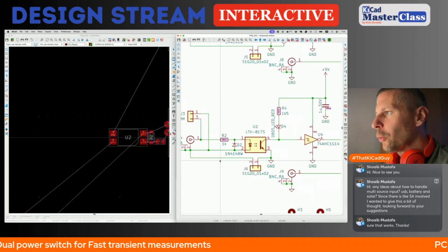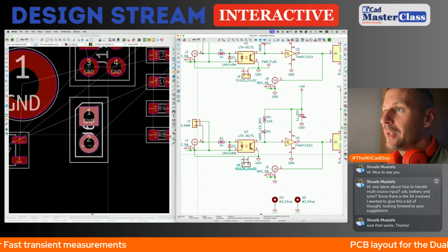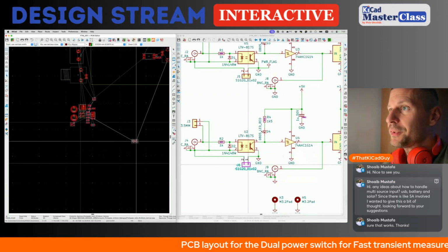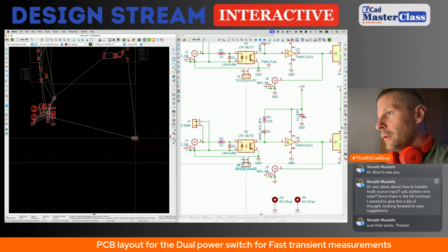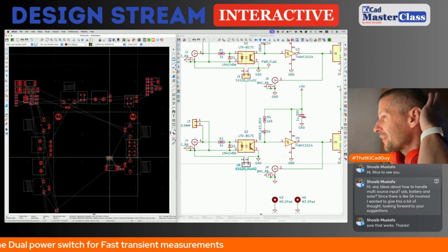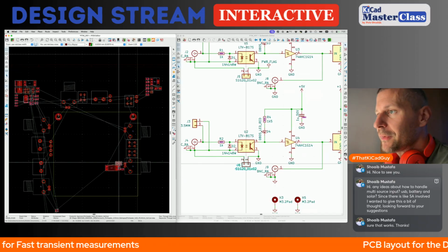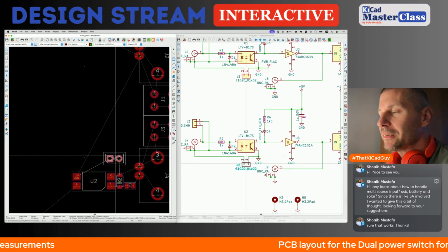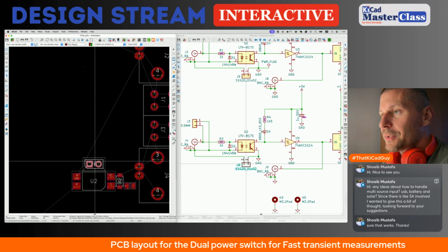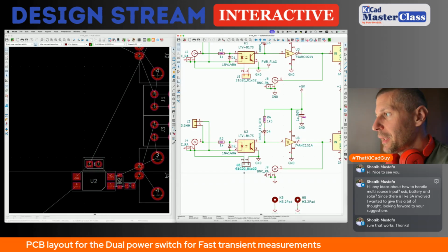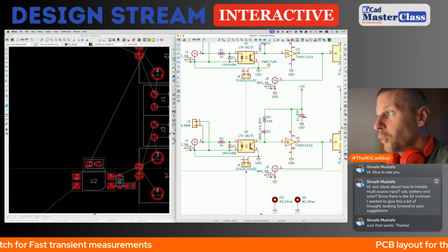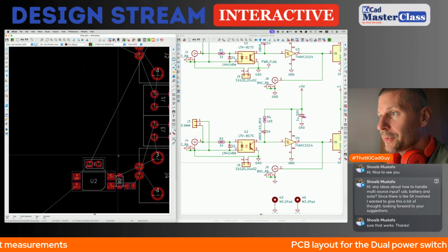I only want to have the possibility to isolate the ground of the waveform generator from the ground of the switch. Because when these 2 instruments are supplied from a different voltage, different mains phase, etc., it can make issues with the grounds. This is why I placed this jumper header, to be able to connect these 2 grounds.